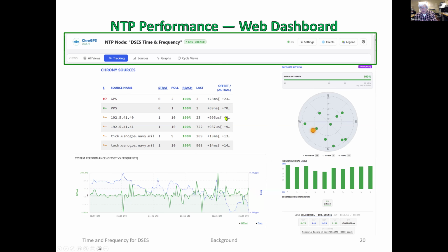And again, it's just prettier and shows more data, and it says the same thing, that the PPS is being used, and we sort of short-circuited here. I should have made it a little bigger, but it's better than the microsecond performance. We have time interval showing that we're in the hundreds of nanoseconds of performance for time service to the computers at Haswell.